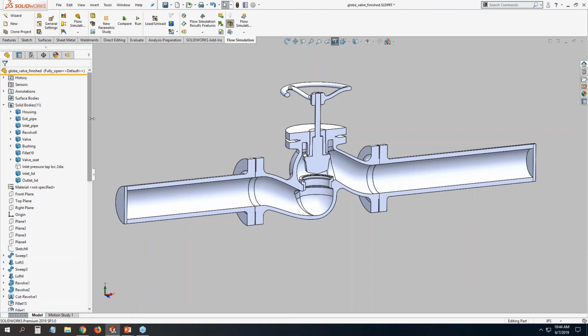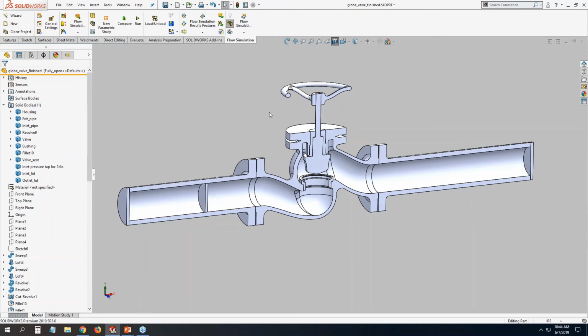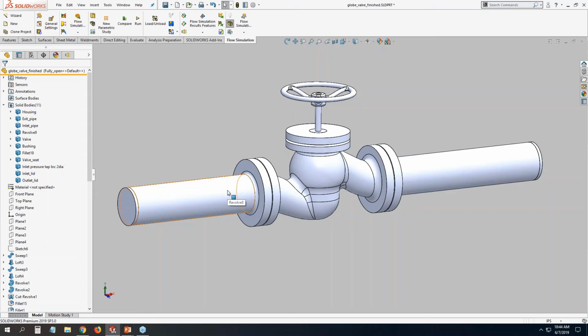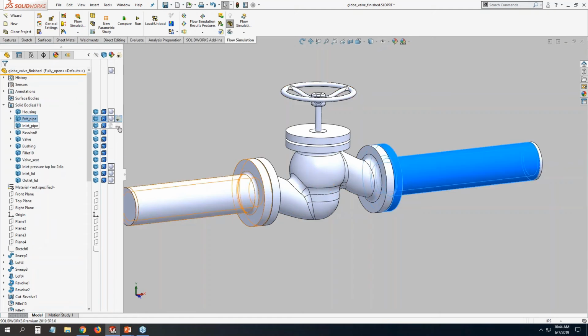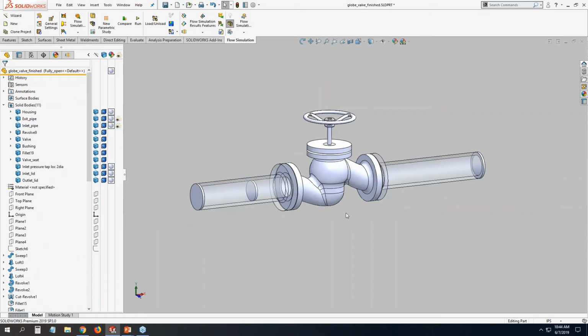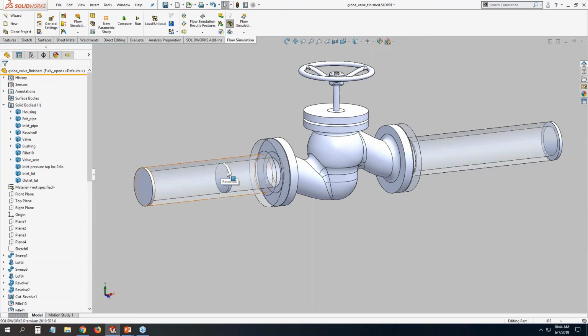And then for this calculation, I have one other part that is hidden here, it's body. And essentially, let me make these inlet faces pipes transparent. So essentially, this is the other part of where we want to do the pressure tap, right? So we're looking for a region which is just 2 diameters upstream of the flow, where we can measure the pressure there.